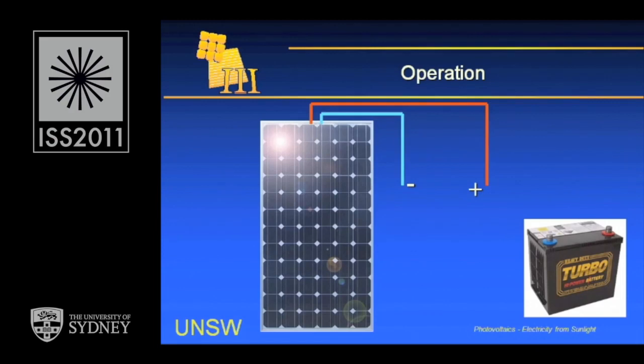So a battery like this might give you 12 volts of voltage, and if you put an appropriate electrical load across it, you might draw 20 amps from it. So the product of that would give about 240 watts of electrical power output. This is about the same as a panel like this will give in bright sunshine. So the two are quite closely related on that account.